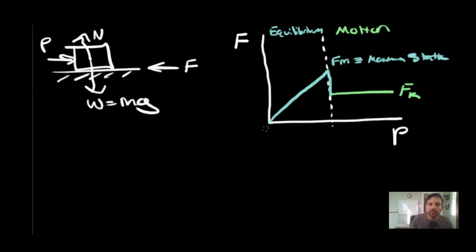So you're increasing your force, and your friction force increases linearly until you reach a maximum limit of your friction, and it breaks loose and starts to slide. Then you are now in your dynamic friction range, where you still have friction but your block is moving, right? I hope that makes sense to you.